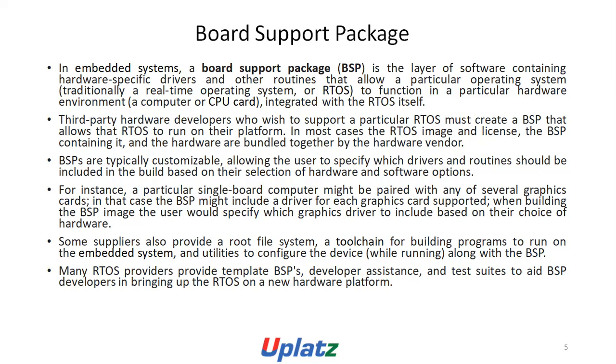BSPs are typically customizable, allowing the user to specify which drivers and routines should be included in the build based on their selection of hardware and software options. For instance, a particular single board computer may be paired with any of several graphics cards. In that case, the BSP might include a driver for each graphics card supported. When building the BSP image, the user would specify which graphics driver to include based on the choice of hardware.